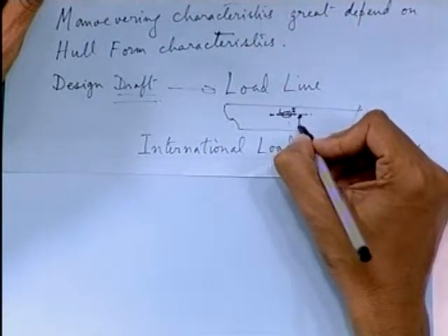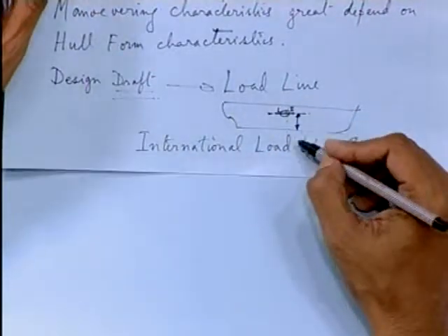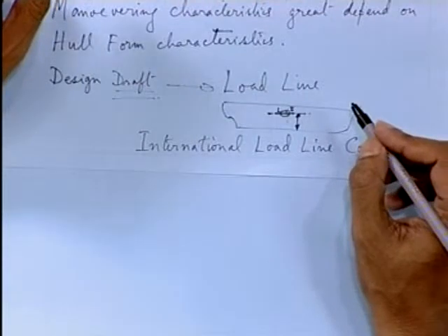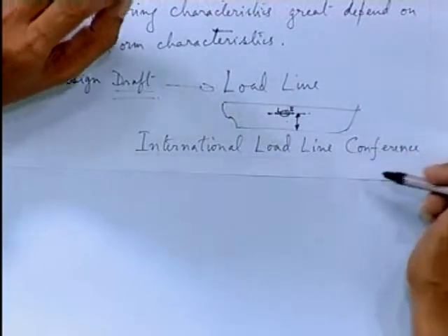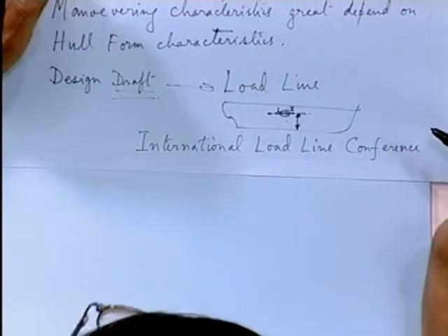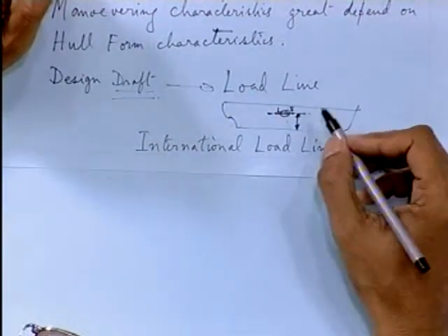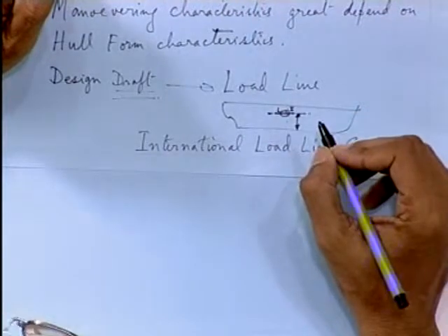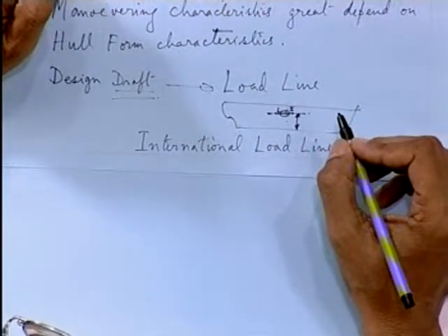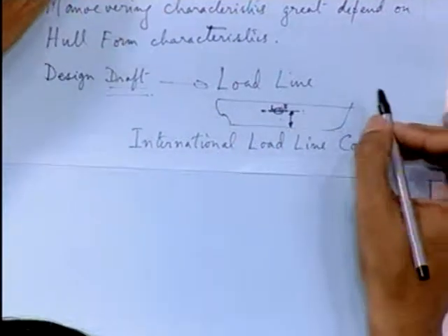The maximum immersion of the ship, which is given by the draft mark, is decided upon at this conference, and then it becomes a rule. So if you are loading the ship, you should not load the ship beyond this mark, otherwise the ship is in danger.